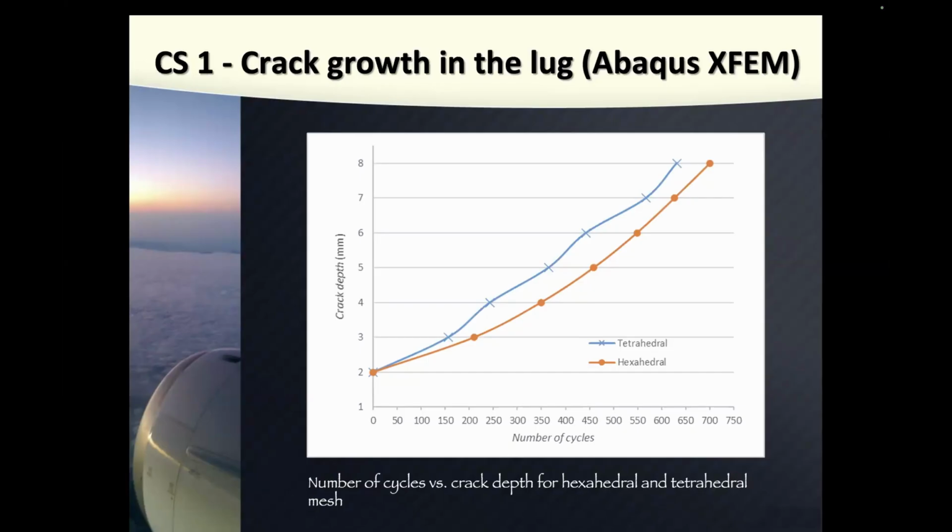So my point is that you have to define the cycle. In this case, a cycle is when you have a maximum load and it pushes your wing up. During the flight, wings are always up. So that's one cycle. Here, 450 cycles of the maximum load means like a couple of minutes.